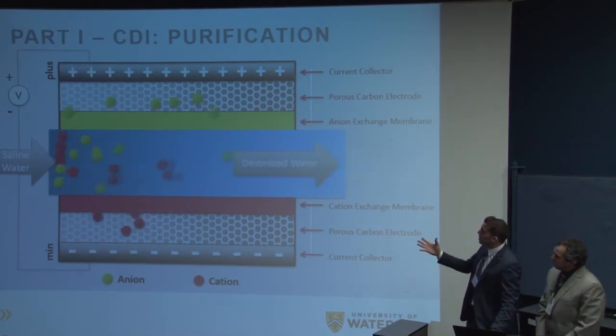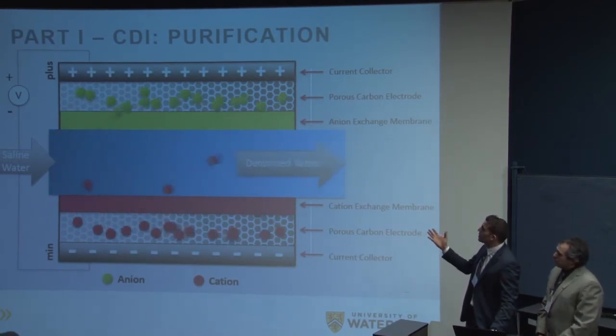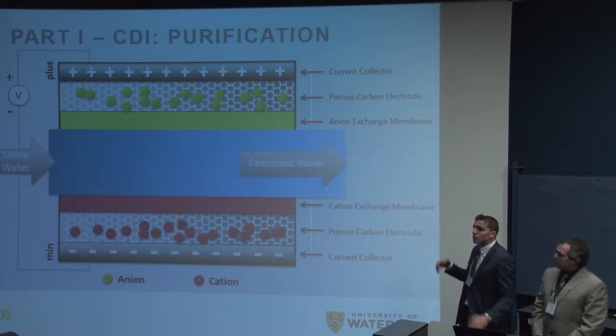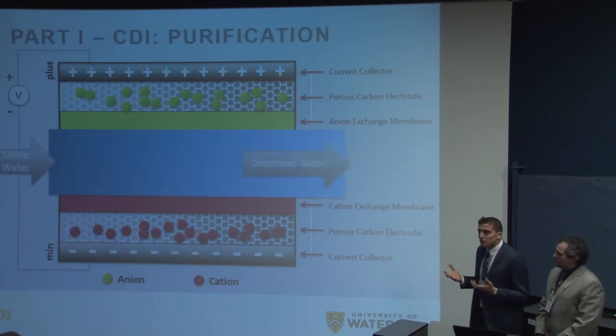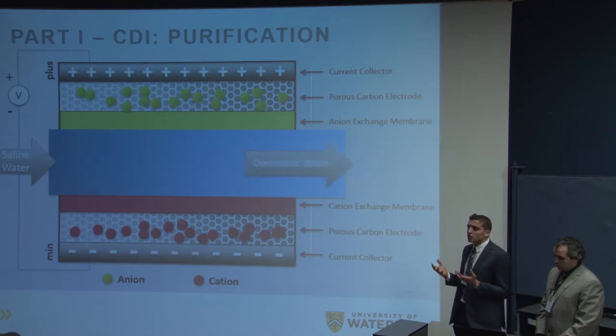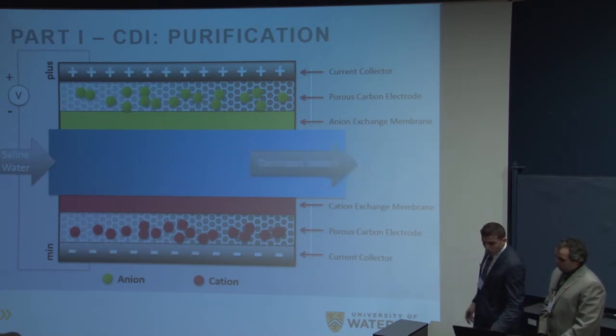So your salt solution comes in, your ions get trapped in the electrode. You end up with deionized water. But of course, after a while, your electrodes become saturated. The concentration of salt ions becomes too much. So then the next stage, as I said, is the regeneration, where